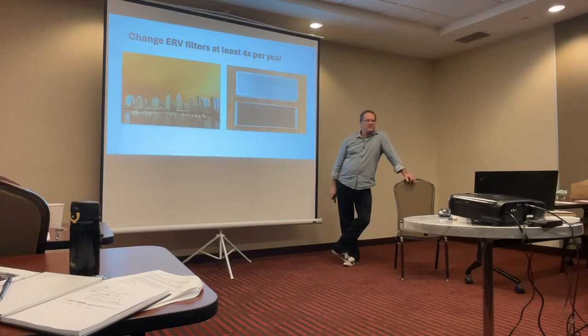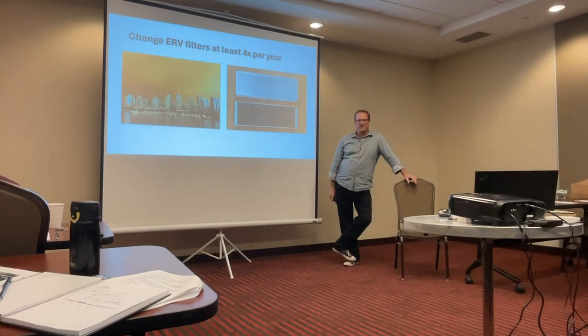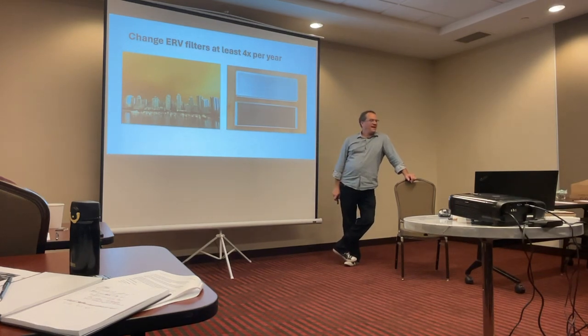That is the huge benefit of Passivhaus. But the entire benefit of Passivhaus goes away if you do not change those filters. The whole Passivhaus thing we're selling, comfort and safety, all this is bullshit if your filter's sitting in there like this for a year. What about the addition of charcoal filters during wildfire season?